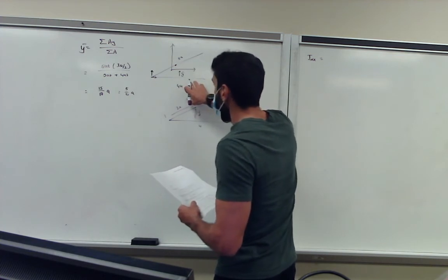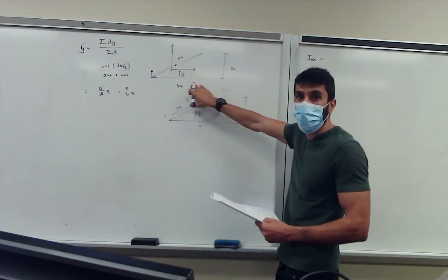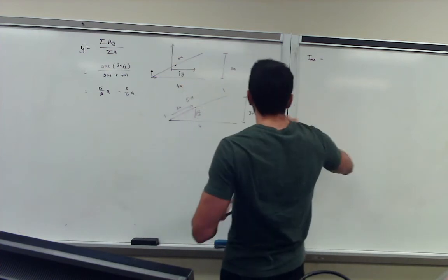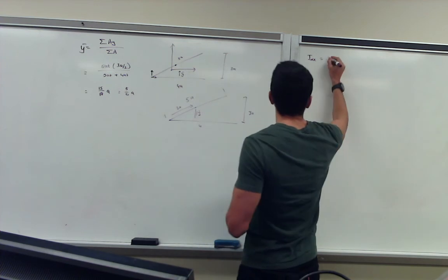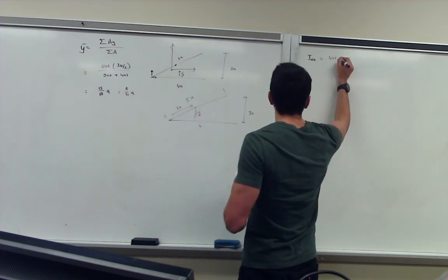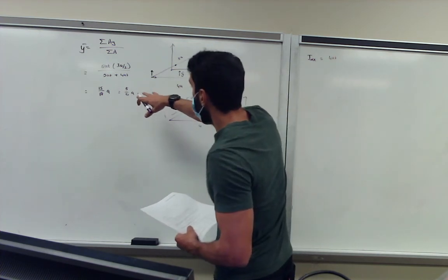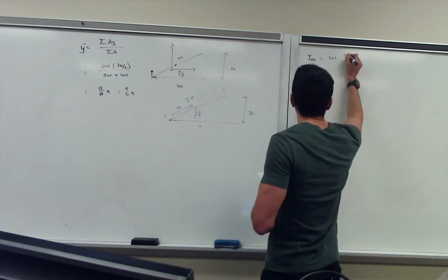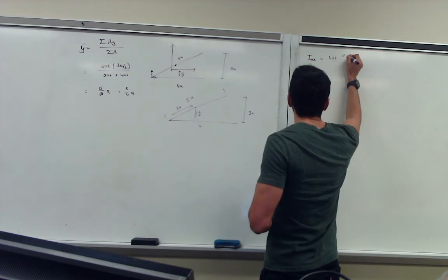So basically, you will get 1/12 times 4a multiplied by t to the power of 3. That one drops, so we only have the standard term: 4at multiplied by y squared, so 5a over 6 squared, so 25 over 36.